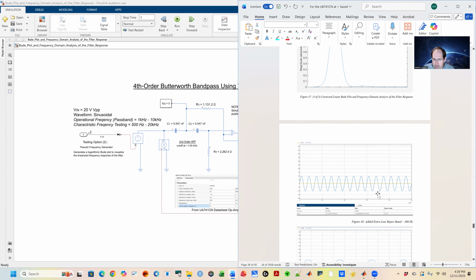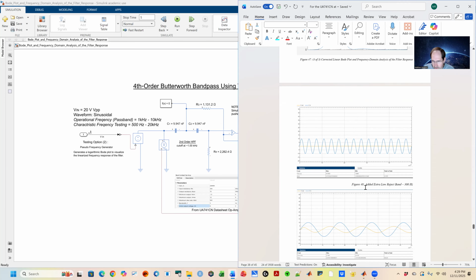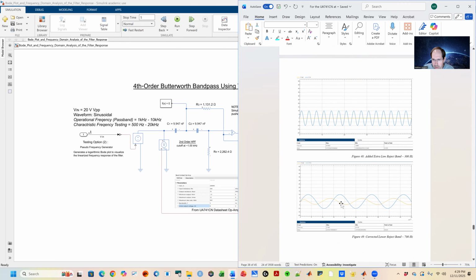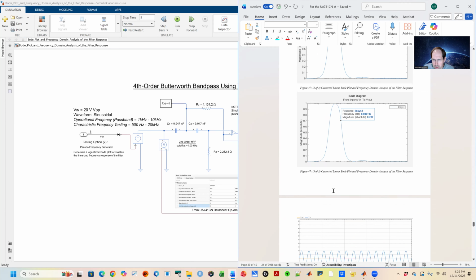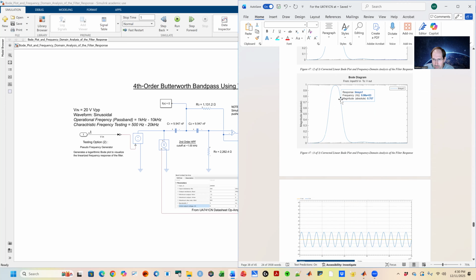So then, as I was telling you before, this right here lets you go over all the different various frequencies. The input frequency is in blue, and the output is in orange. And I went through specific key bands and looked at each of them so that you could see there's attenuation here and gain right here of 1.